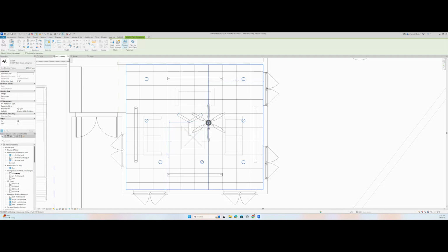Just be careful because here it is looking for the surface from the table, right? So keep on the surface of the ceiling. Look, you see, it's using faces, right? I can choose the work plane. It might get me fewer problems because I can move it easily, right? Around, and I can place it anywhere. But if I switch to faces and I get the face on my sofa, it's gonna try to place it around my sofa. So be careful with that. So let's use place on work plane.